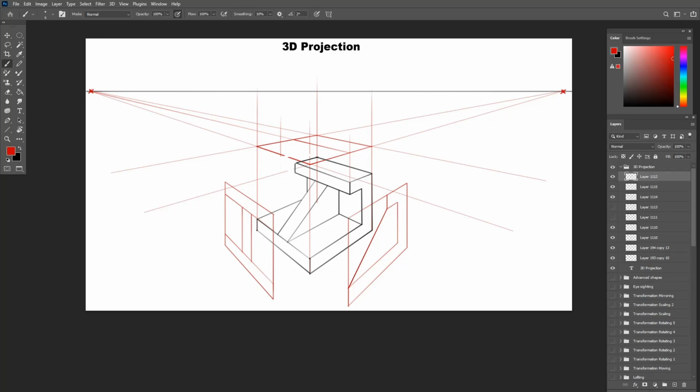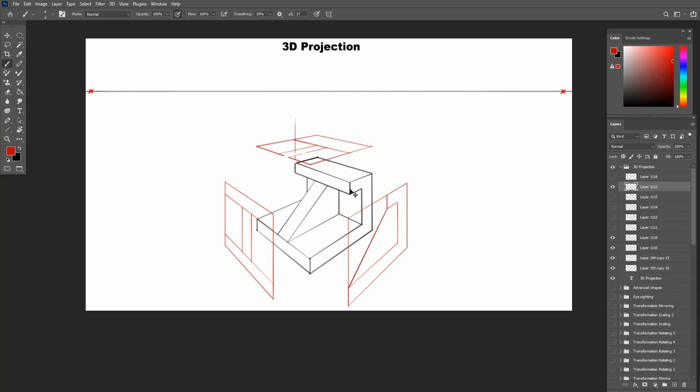What we will see here is the top ledge and the connecting slope in between the ledge and the bottom platform. The only detail we can add is the hidden line between the back wall and the top ledge, which will show up as dotted line in the middle of the top ledge.